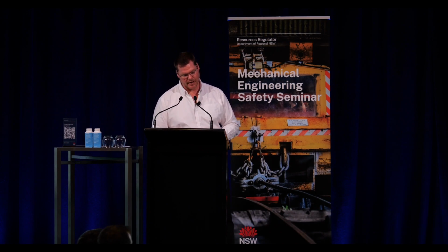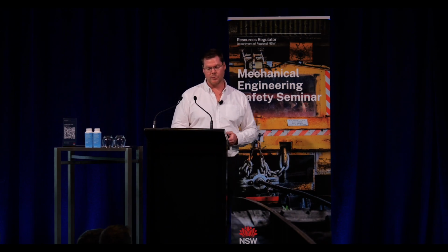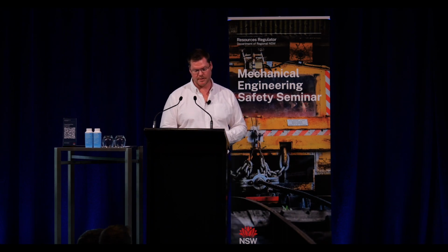So excessive fleet angle, greater than the design capacity of the sheave, the drum or the rope, can rapidly deteriorate the rope, leading to reduced life of the rope, sheave or the drum, and potentially lead to catastrophic failure.